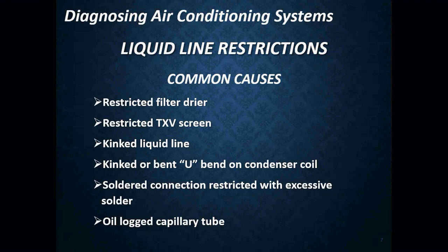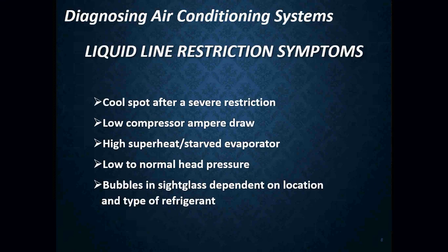When it comes to these things, you have to take the correct readings. You have to take superheat readings. You have to take subcooling readings. If you don't do those things, you're going to miss some vital pieces of information. Okay? Now, symptoms of a liquid line restriction.